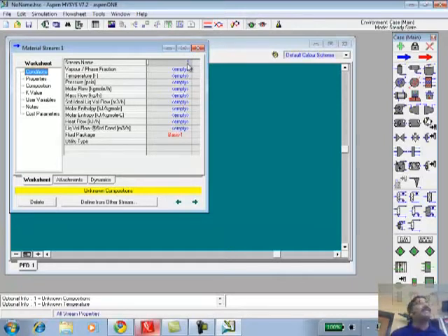It tells me already I'm dealing with stream 1. I press this, for example, and enter 0.5. So I'm asking this process to produce, that stream should have 50% as vapor. Okay? And then I'm going to specify anything that is in blue, you can specify. And I'm going to specify the pressure. So I click on the pressure and specify 1. And then it tells me what are the units. What is the unit of that 1?